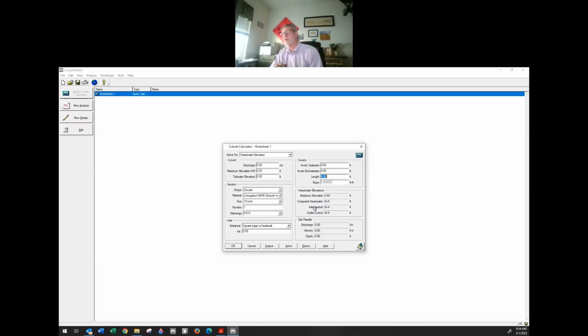So you could use your judgment there, saying that even though the math is telling you that this could be a problem, historical evidence in this situation would say it's okay to go ahead and move forward with that design and leave it at the 2 foot. But you want to make that decision very, very carefully. 99% of the time, you're going to be using the maximum allowable, and you'll just stick with that. So if you have to exceed that, be sure that the PE is involved. The computed headwater, inlet control, outlet control, those are nice to know information, but you won't need it.